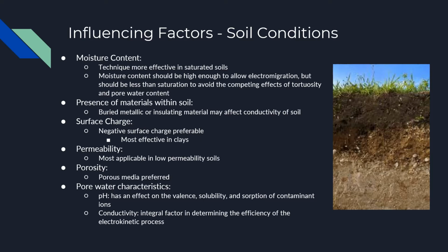When looking at the pore water characteristics, it's important to know the pH and conductivity that the pore water has. This is because the pH has an effect on the valence, solubility, and sorption of the contaminant ions, and the conductivity is an integral factor in determining the efficiency of the electrokinetic process.